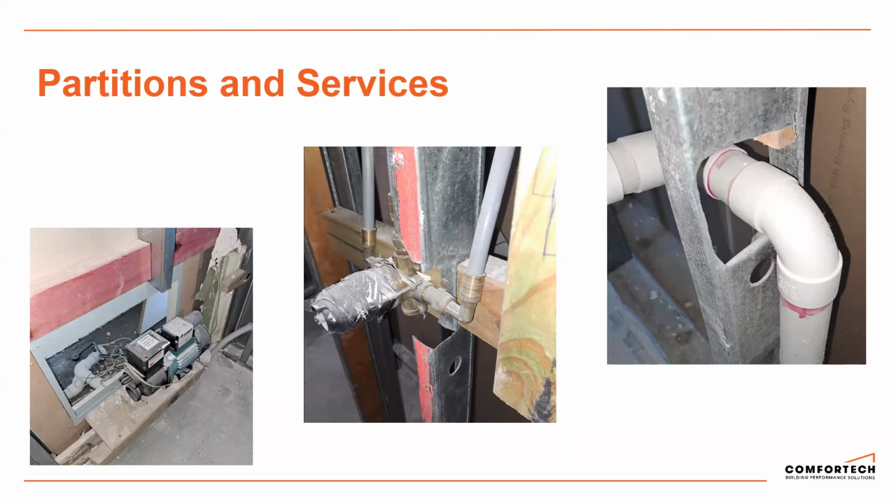The right-hand side there, you can see there's a pipe running through a steel stud. You can cut holes in steel stud, no issues with doing that. But again, there's parameters you need to follow. The other question is why don't we bring that pipe up in between the studs so we don't have to cut a big hole in it? So again, have those conversations early doors. If this kind of stuff's going to be involved in your project, it's really important that these are highlighted so that someone doesn't have to come and try and fix it up otherwise.